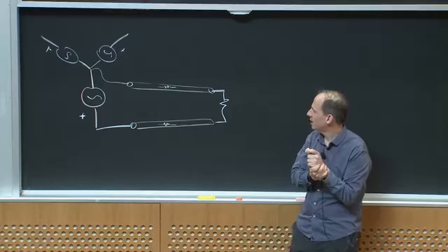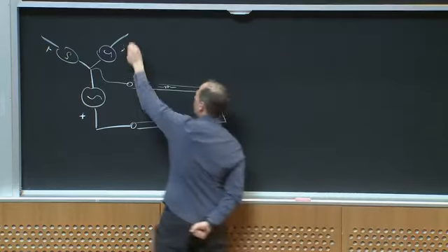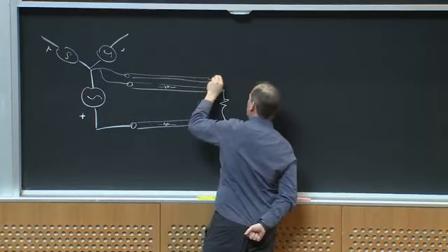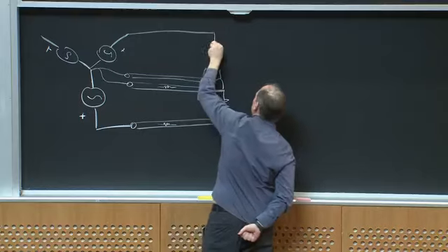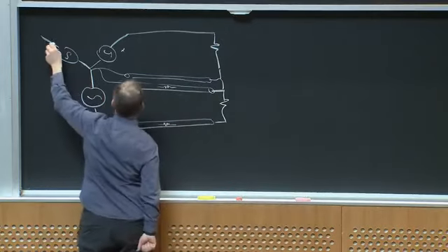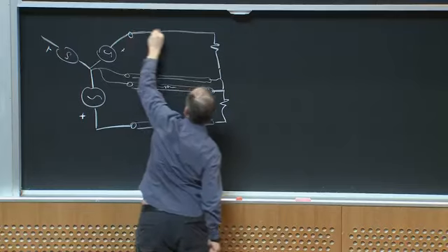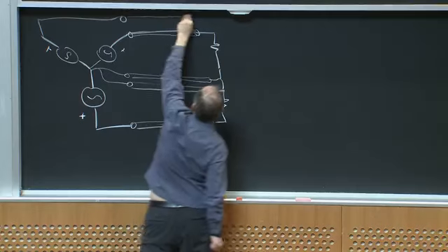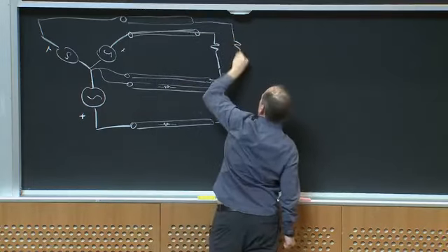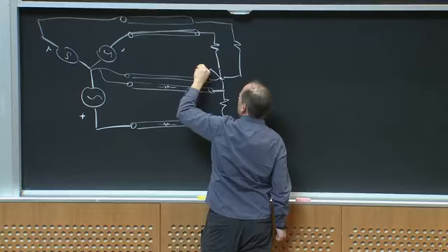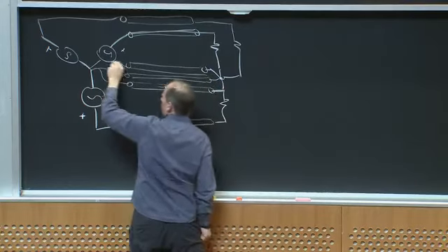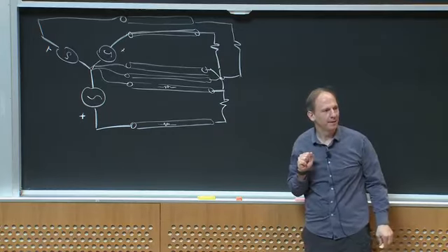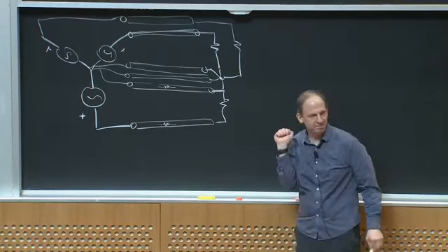Okay? But suppose I say, okay, let me use 2 other phases. So here's my other conductor here, and maybe I'll connect them on this side as well. Here's another one, and I'll do my third one. So I'm sending current out this wire and back this wire. And then I'll do my last one. I'll send current out this wire, and I'll send current back through this wire as well. Okay, so now I'm transferring 3 times as much power, if all the resistors were the same.